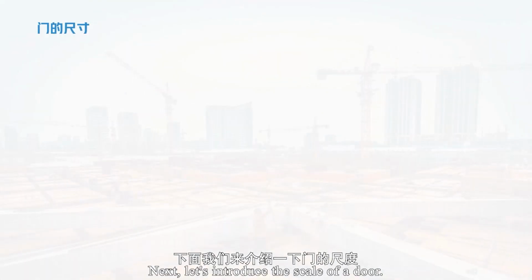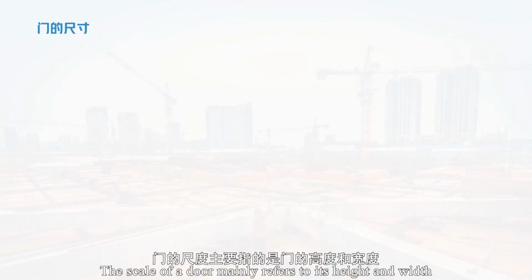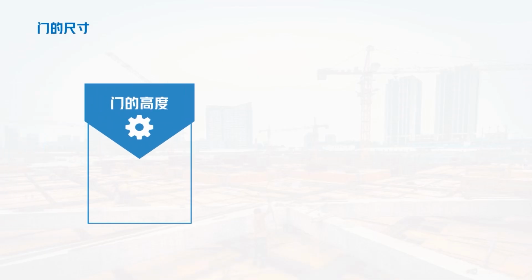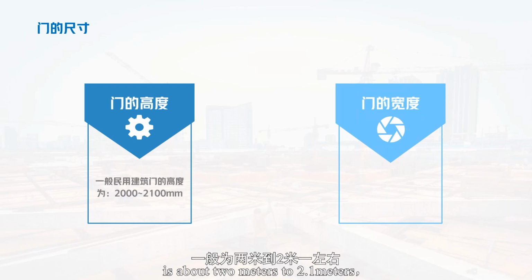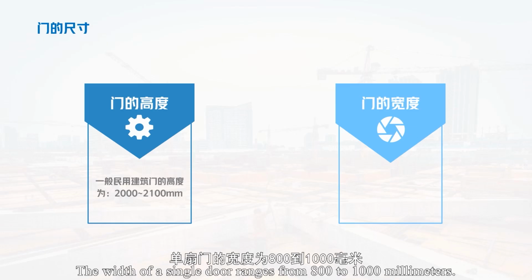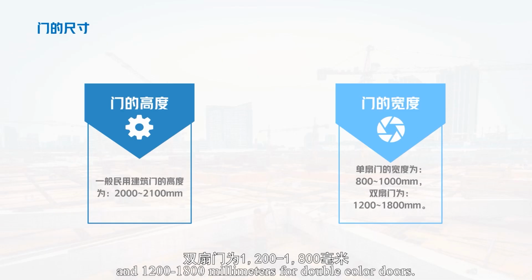Next, let's introduce the scale of a door. The scale of a door mainly refers to its height and width. The height of doors in general civil buildings is about 2 meters to 2.1 meters. The width of the door. The width of a single door ranges from 800 to 1,000 millimeters, and 1,200 to 1,800 millimeters for double doors.